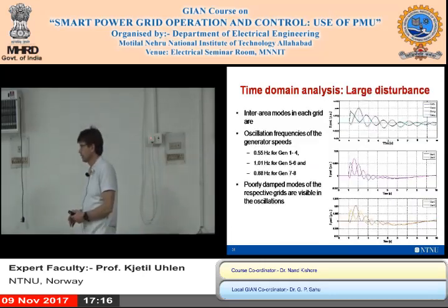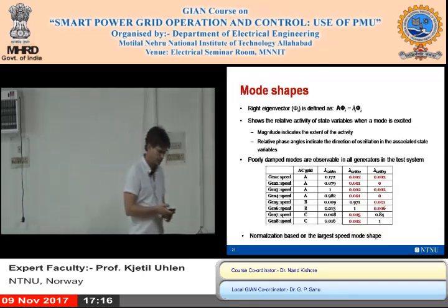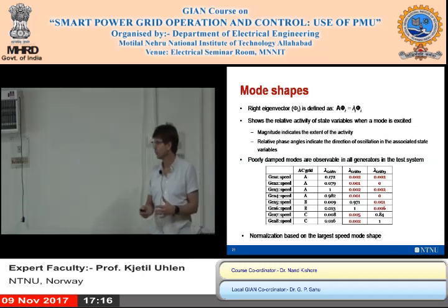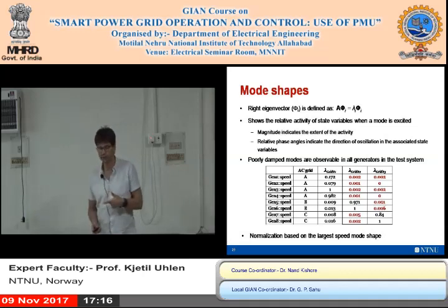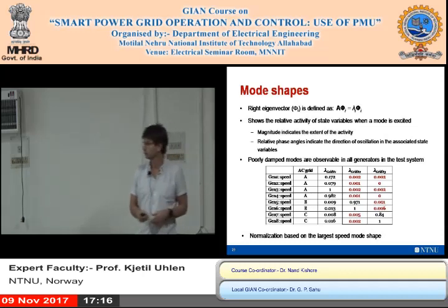And the main point here is that the interaction depends mainly on the control system. So the faster and tighter control you have, the less interaction you have. But if you want to exchange reserves and you want to apply DC voltage control, then you also have the interactions. But of course, that is a result of the fact that you actually want interactions. You want to interact.